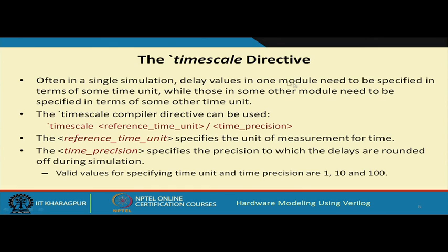Now, with respect to some module, you may have to specify some delay values, but for some other module the delay value may be different. So, it is always good to have a timescale declaration at the beginning of every module.